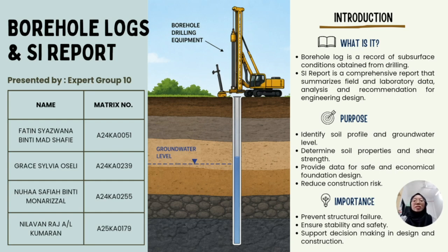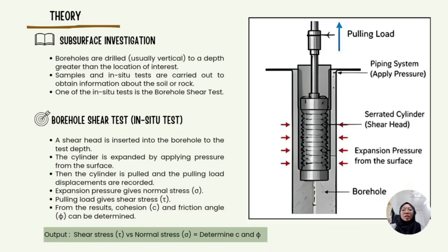So what is the purpose? The purpose is to identify the soil profile and groundwater level, determine soil properties and shear strength, provide data for safe and economical foundation design, and reduce construction risks. So what is the importance of borehole logs and the SI report? They can prevent structural failure, ensure stability and safety, and support decision making in design and construction.